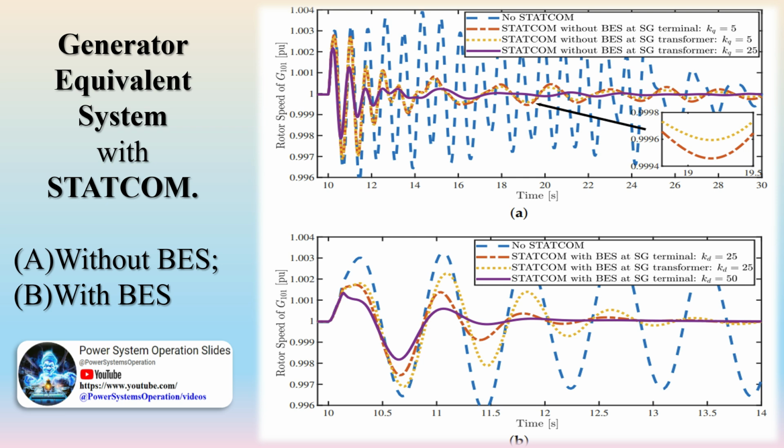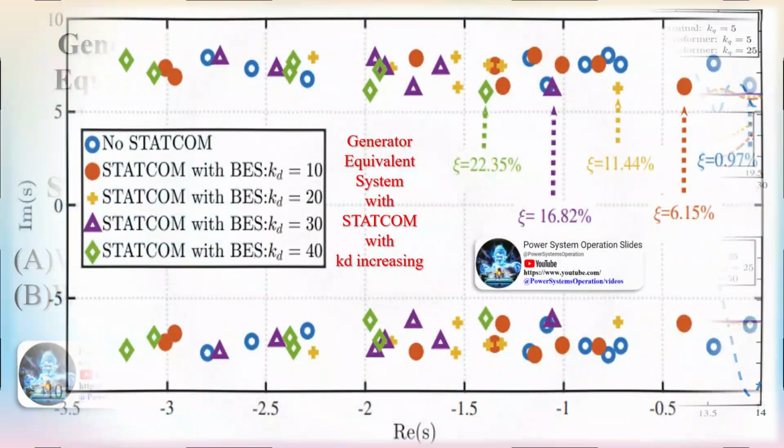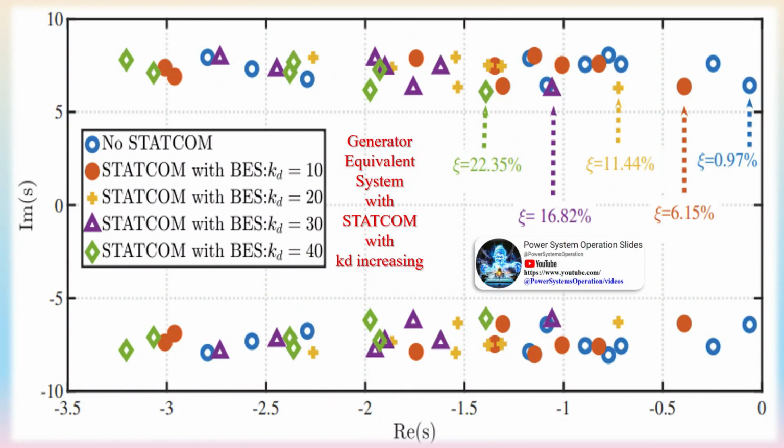When system voltage is high, the STATCOM will absorb reactive power, inductive behavior. When system voltage is low, the STATCOM will generate and inject reactive power into the system, capacitive. Subsequently, the amount of reactive power flow is given by the equation. VAR control. In this mode, the STATCOM reactive power output is kept constant, independent of other system parameters.